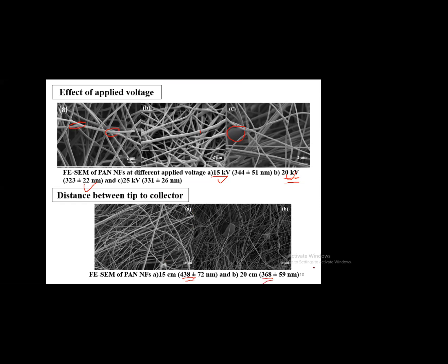If we go again to 25 centimeter, what will happen? The fiber will be very small and it will break. There is a chance of breaking of the fiber. Continuity will break here. But at 20 centimeter, the fiber will be drawn continuously without any breaking, without any formation of knots. So the important parameter is the viscosity of the solution.